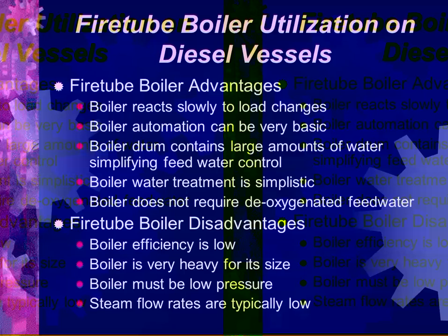Now, fire tube boilers, I've never seen one built over 300 pounds. It doesn't mean that they haven't been done, but I would assume most of them at about 150 psi would be fairly normal. They're low pressure. Well, for heating services, you don't need a high pressure boiler, so that's perfectly adequate.